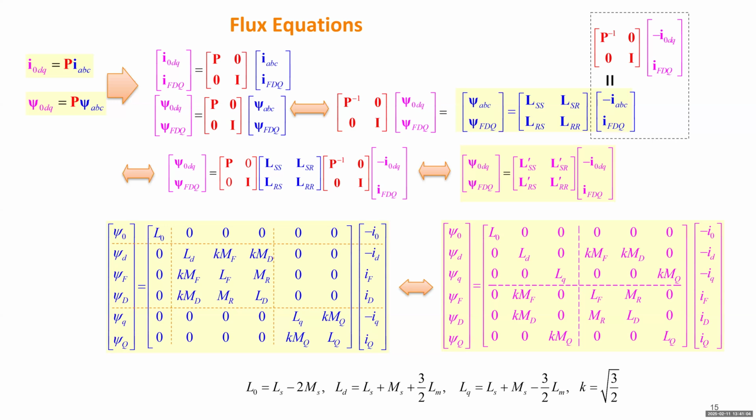So we change all the L to capital because that's constant. We use lowercase to represent the variable. They just indicate the self-inductances. And in this block, everything is M, right? Because this block represents the mutual inductances between the stator winding and the rotor winding.